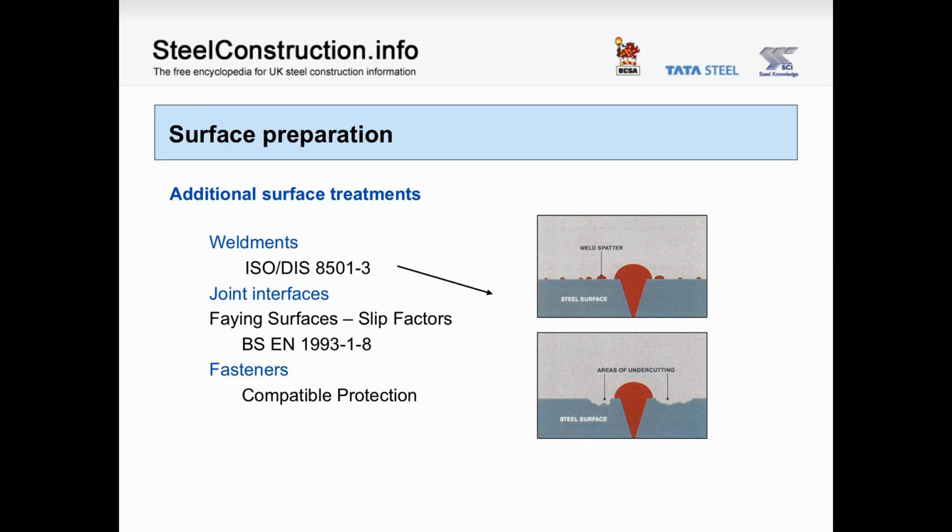Depending upon the specific requirements of the structure, it may be necessary to remove general imperfections on welds such as spatter, rough profiles and cut edges to produce an acceptable surface condition for painting. Weldments on fabricated structural steelwork represent a relatively small but important part of the structure and can produce variable surface profiles and uneven, sharp surfaces and projections that can cause premature coating failure.